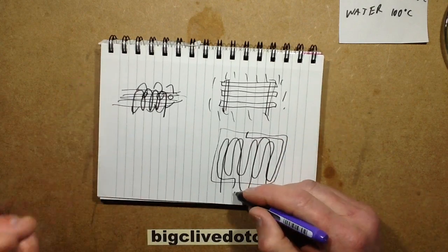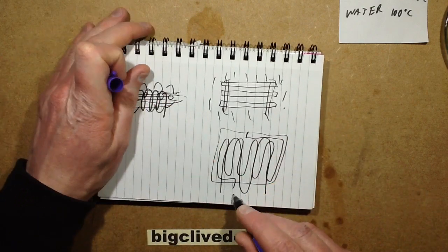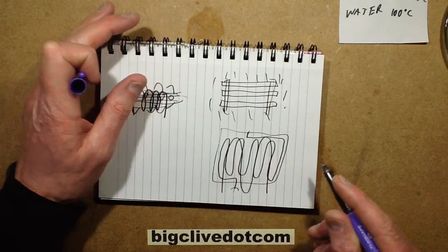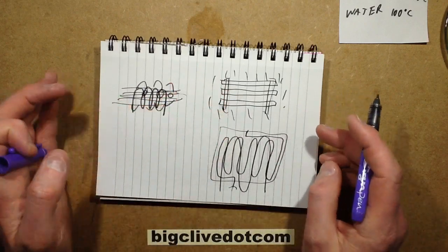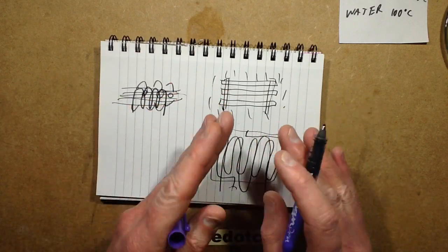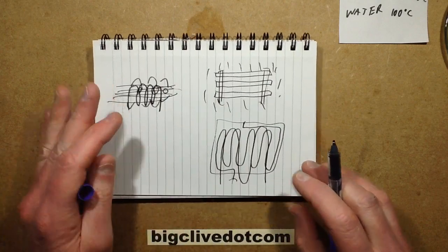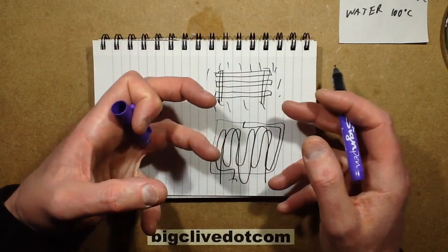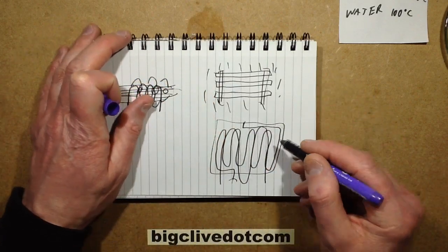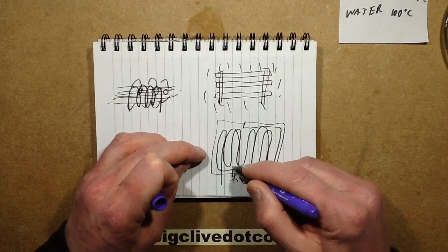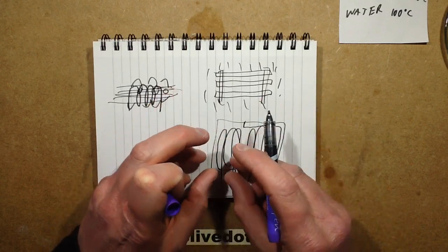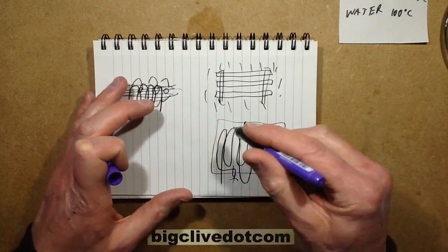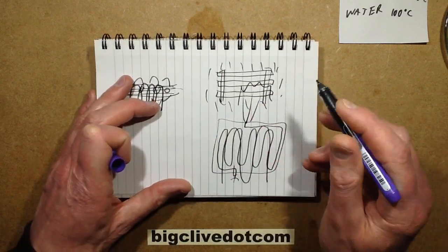And what happens is the mixture of the glycol and the water gets squirted in at a pressure from a wee solenoid pump into this copper pipe, and this block is heated up to a very specific temperature. There's a wide tolerance to the temperature, it's not that bad, as long as it's sort of the point it's going to basically evaporate all the water without burning the glycol. That's the main thing. And that causes, as the liquid travels through, it immediately explosively atomizes, and because of the large length it has to go through, it makes sure that most of it is atomized, and it comes out as that big plume of steam out the other end.